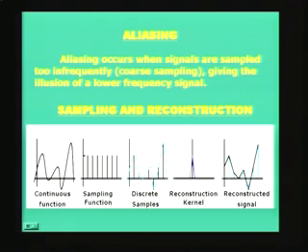I have taken a very shallow ramp function, which if you convolve with this function, you will get a reconstructed signal like this. So, this is an approximated reconstructed signal of the continuous function which you see here, and you can almost see the effect of discontinuity, the coarseness in the signal represented in the discrete digital domain corresponding to the analog 1D analog continuous domain here.